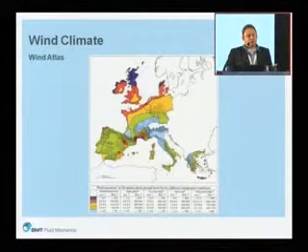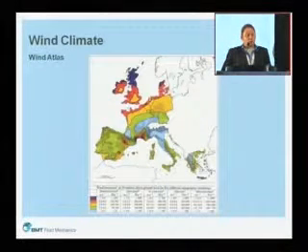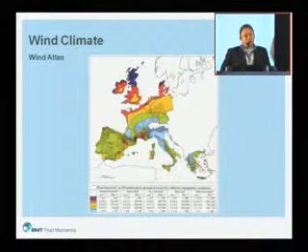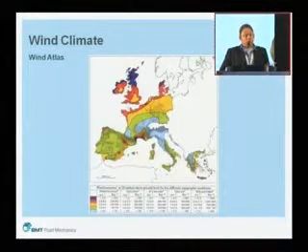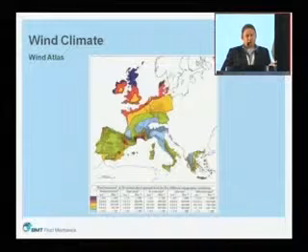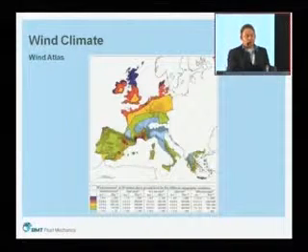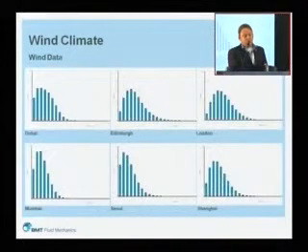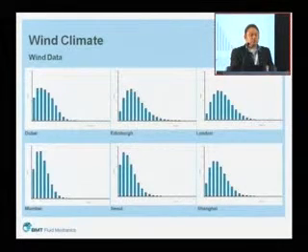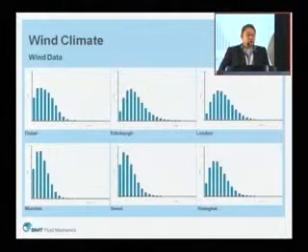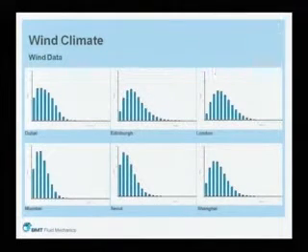Considering wind climate, if you were designing a wind farm, normally wind farm designers go to wind atlases. They're well established and tell you what the general wind speed distribution is, and from that you can immediately estimate your wind energy yield. If you're considering putting wind turbines on buildings, you need to do something a bit more sophisticated in your wind analysis, and that really starts with obtaining reliable long-term statistics for wherever your site is.